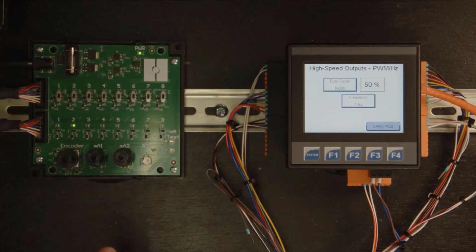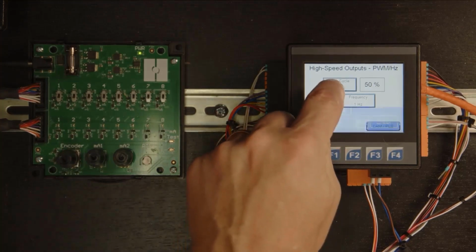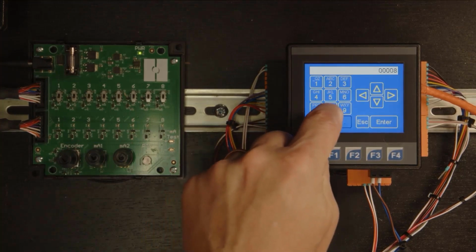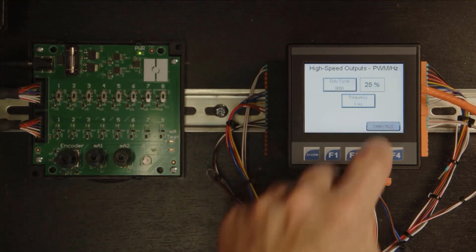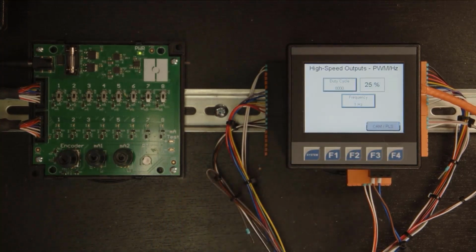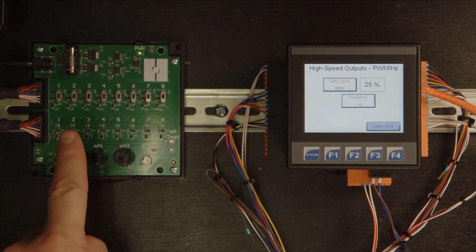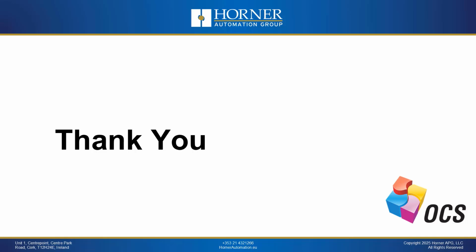Now let's say we want a 25% duty cycle. Then we should change this down to 8,000, because 32,000 equals 100% duty cycle, so 8,000 would equal 25%. And you can see we are flashing at 1 Hz, but the output is only on 25% of the time.